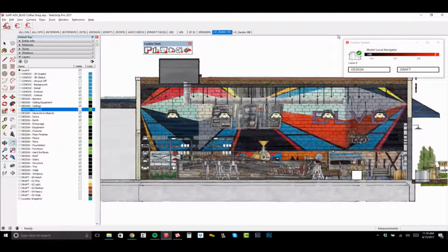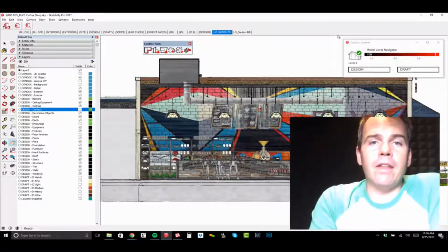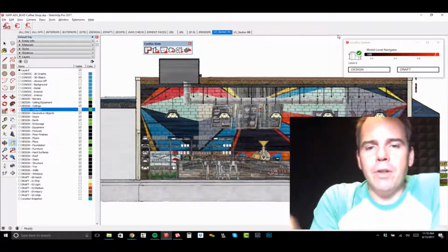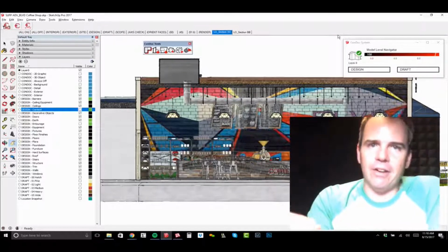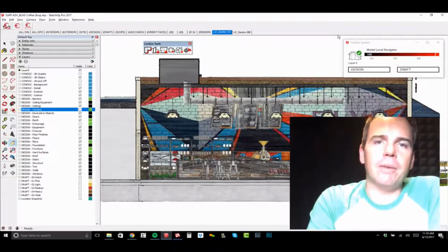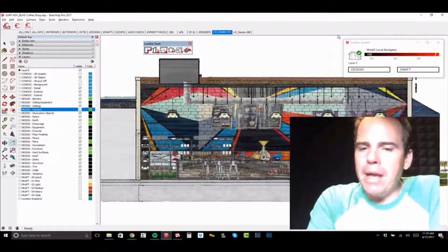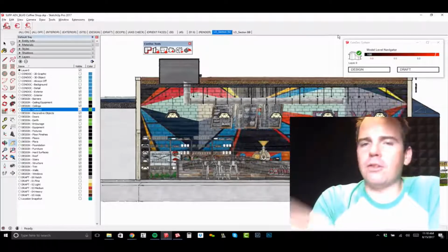So a quick point here. ConDoc Tools are going to drastically automate layers, styles, and scenes, but that doesn't mean that you can't go in there and kind of tinker with what we've created. So just like I did there, it did the broad strokes, and then I just have to figure out, oh, I don't want to see context in this particular section. Let's just turn that off and update my scene. So it's a major jump start. Hopefully out of the box it gets you where you want to be, but certainly it's customizable.